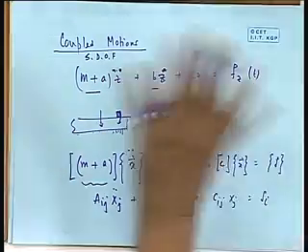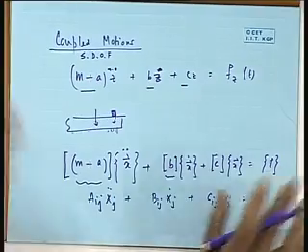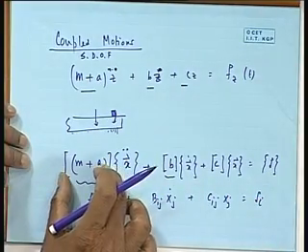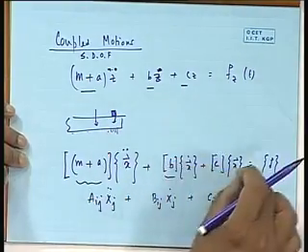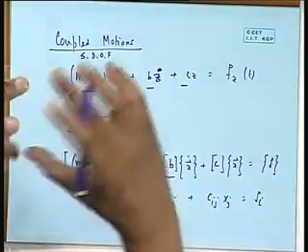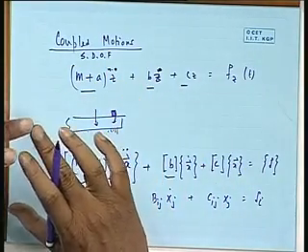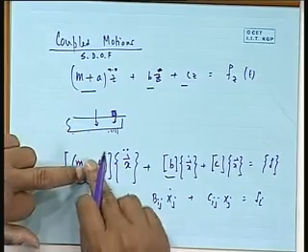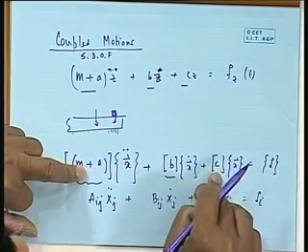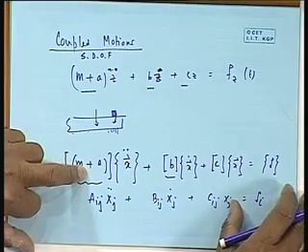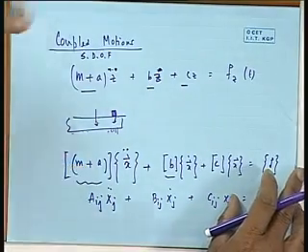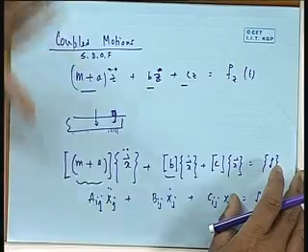So, in other words, when you want to solve this equation of motion, you have to end up solving this equation, not one. Earlier we said that you find out this, this, and this, and you can solve it as a single degree of freedom. But in reality, you have to find all of this, which has 36 elements, 6 by 6. It is a big matrix. This full thing will be a set of 6 coupled equations with a number of coefficients. So you find out all the added masses, all the dampings, all the restoring forces, then you get this. This is how it is. Okay, this is just for the sake of completion, especially as I said, heave and pitch is important.